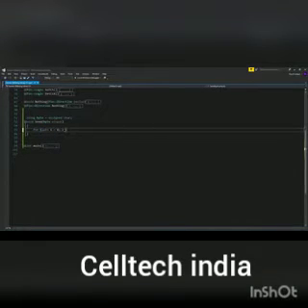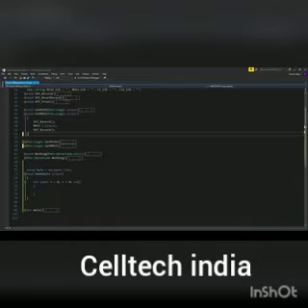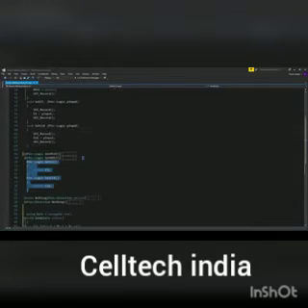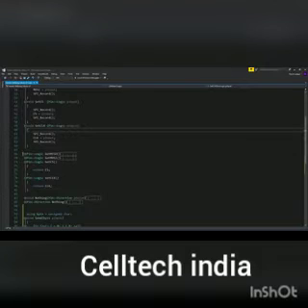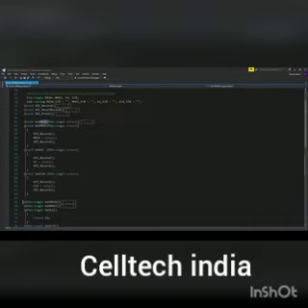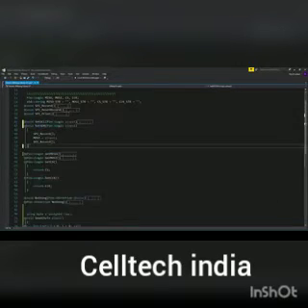So the first thing I'm going to do is write this send function. The send function is a basic for loop which sends 8 bits, and this is going to be the fundamental thing that sends the address and the data and all that kind of thing. It does a few different things, and it accesses GPIO through functions instead of actual pin set and clear calls.